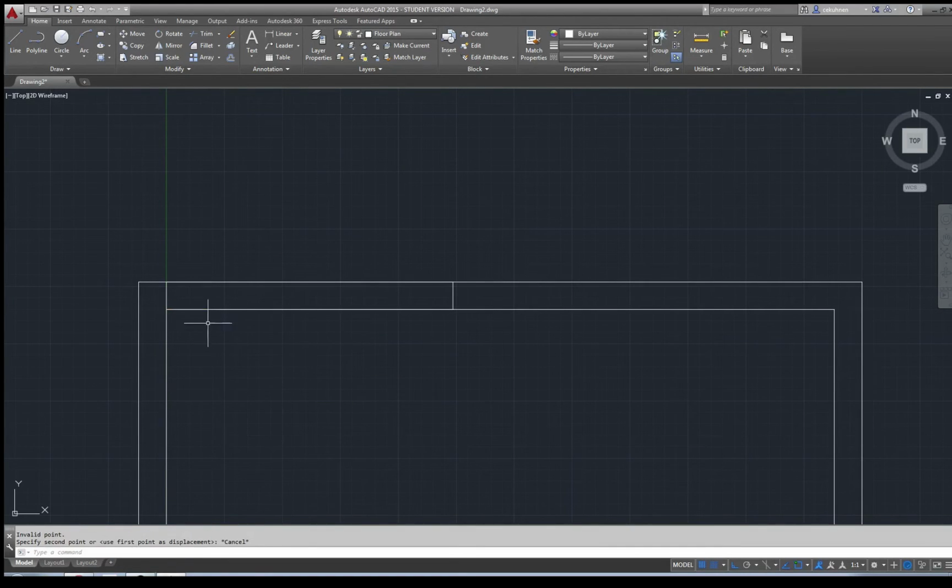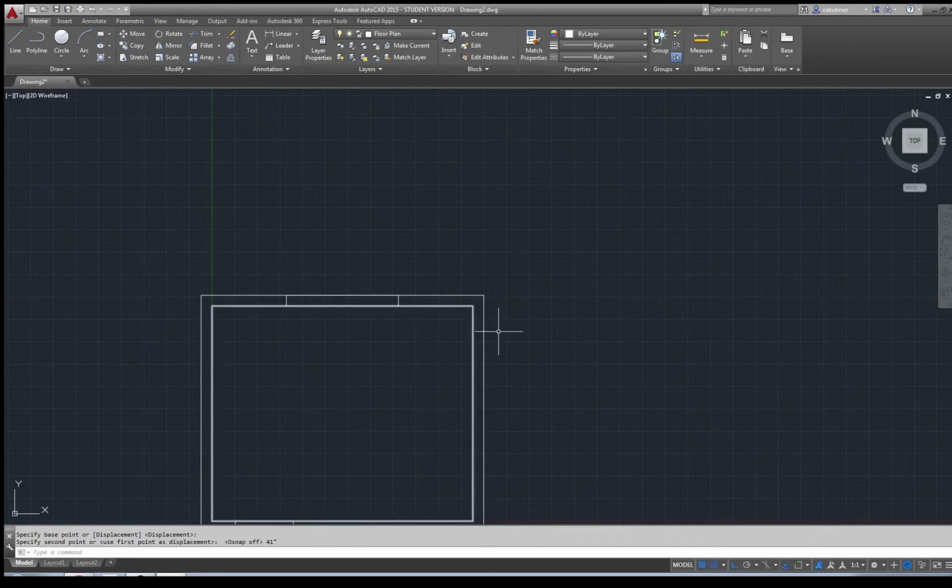And this is actually a nice case about sometimes the snapping tools becoming really annoying. So one more time, I click my object, spacebar, I select from where, turn off the snapping. See, I'm still in orthographic, so it's very easy to just move it left and right. 41 inches, enter, there it is.